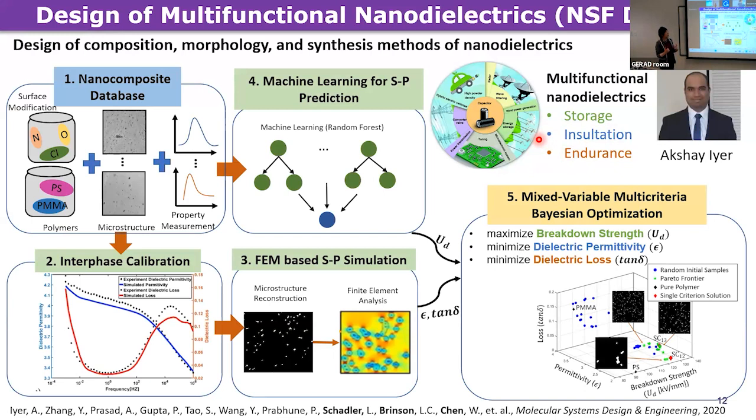This is from the dielectric point of view, good insulation, and then good mechanical endurance. This problem actually involves a lot of trade-offs, because from the mechanical point of view, a stronger material is one where you put in lots of particles that reinforce your material and make it stronger, okay? But if it's too dense, you are going to sacrifice your dielectric behavior, okay? So it's multifunctional, meaning multi-objective. On the other hand, we have decisions we need to make, like what kind of polymer we should use, that's the base matrix, and what kind of surface treatment.